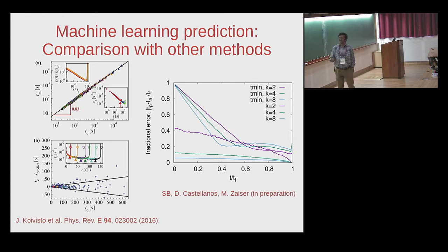One such thing is this U-shaped curve in the strain rate. If you plot strain rate with time, you have a U-shaped curve. And the minimum of that curve is supposed to have a linear relation with the failure point. For a sufficiently simple model, you could analytically show that. For a sufficiently complicated model, you can't, but you still have this linear relation. And you could just say that once we reach the minimum, we know where the failure point would be.